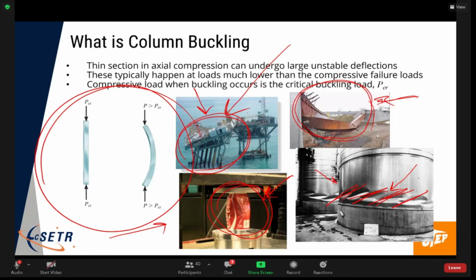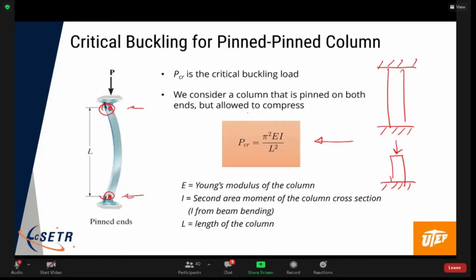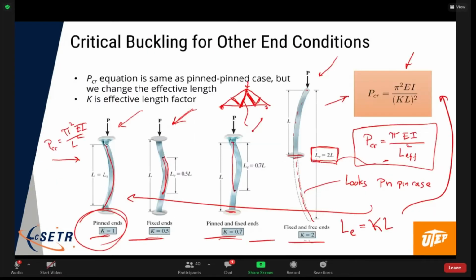But again, that's pretty easy to do. It's just the same problem, but applied to each compressive element in the truss. If the element is in tension, if the internal force is positive, you don't have to worry about buckling. There's no buckling in tension. It's only in compression.